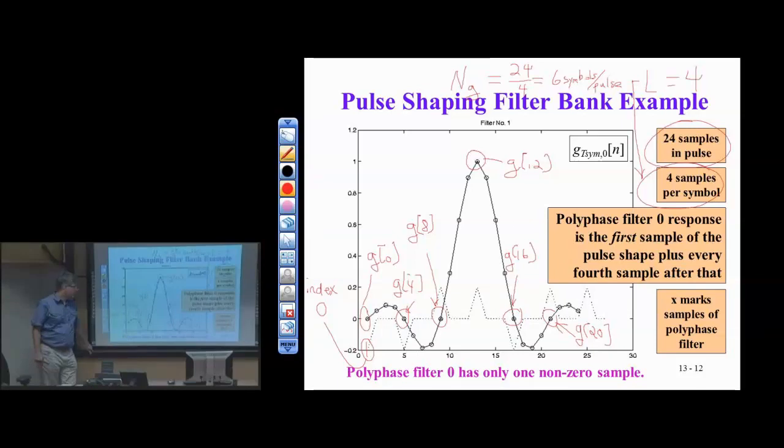So this would be the FIR filter fully loaded, fully responding to the input. Normally the initial values are 0. These are coefficients, but separately we have the initial values in the tapped delay line. They're zeroed out as a necessary condition for LTI properties. So I'm going to buffer 3 symbols before I do any transmission. Another way to think about it is that whatever comes off of the FIR filter or the polyphase filter bank version, I'm going to throw out at least the first symbols, because the pulse shaping filter hasn't fully responded yet. You throw out the group delay, in other words. You want to throw out the first 3, which is the group delay, half the samples, basically.